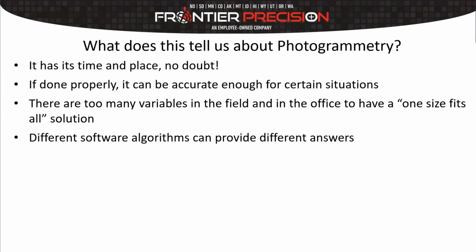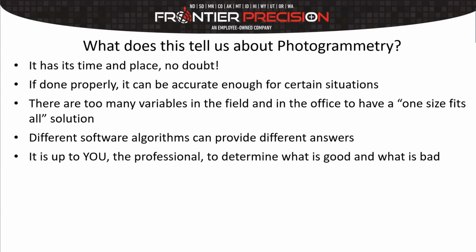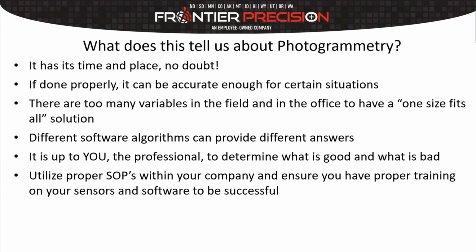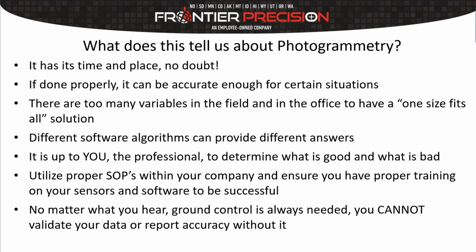So, you have different software algorithms, as we just saw here, will provide different answers. So just keep in mind, it's up to you as a professional to determine what's good, what's bad, what should I use. One of our recommendations that we do here is to utilize proper standard operating procedures within your company, just to make sure you have proper training on your sensors and your software, and everybody's consistent and doing the same thing. And then no matter what you hear, you always need ground control.